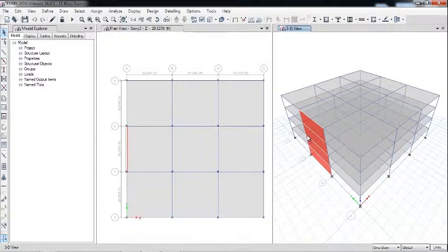So to make concrete walls act like columns, to take in plane moments, to carry all the moments from slabs, take them themselves and then move towards the ground, we have to assign the concrete walls pier labels. So how do we assign the pier labels?